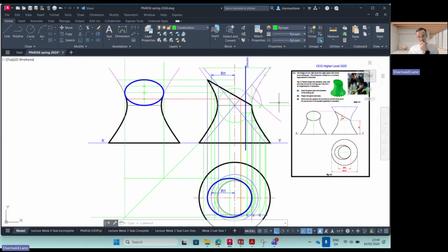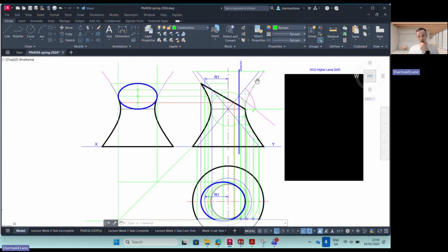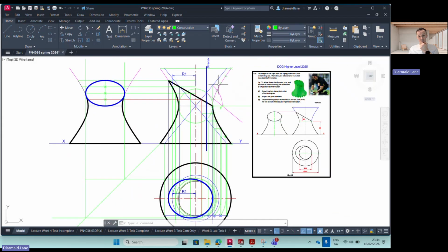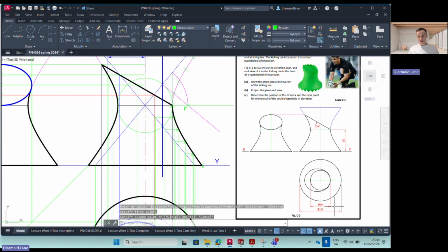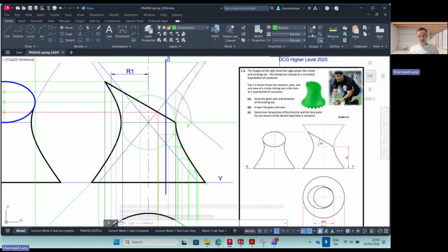While this is quite packed looking, I think it's pretty straightforward, just to show you. So we have the question here. 55 millimeters up is the distance from the base circle to the throat circle, which you can see here. It's also given in the question that 104 is the base and 50 for the throat. So we can see that 104 is your base, and your throat circle here in the center is 50 millimeters. So that's all good there.